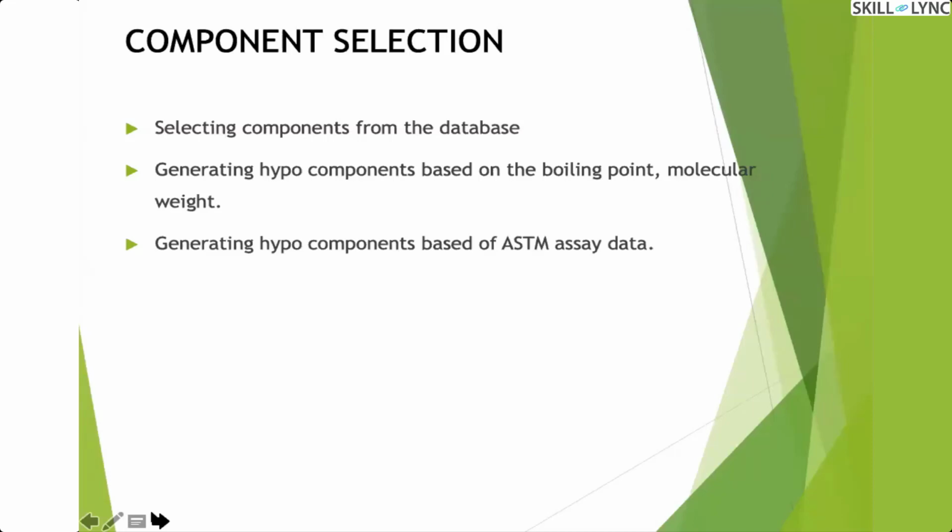The vapor keeps coming out of the liquid, so you condense those vapors and calculate the percentage of liquid which is getting vaporized. Say 5% is vaporized, you note down at what temperature, and then at what temperature 10% of your liquid, like 10 ml, has vaporized.